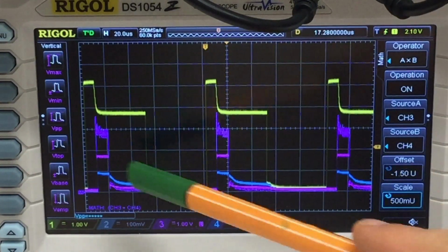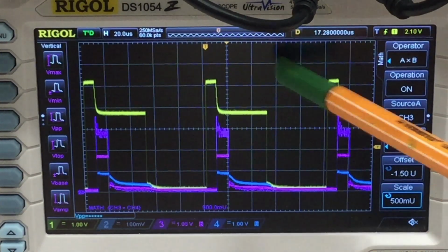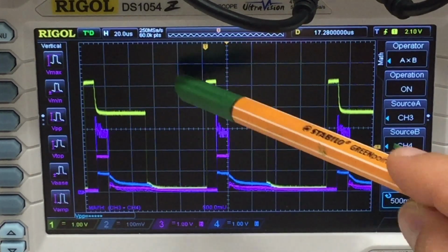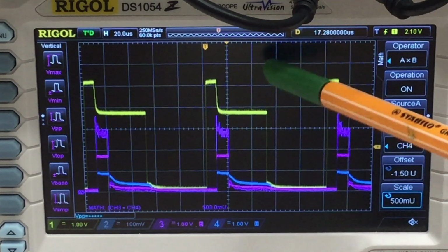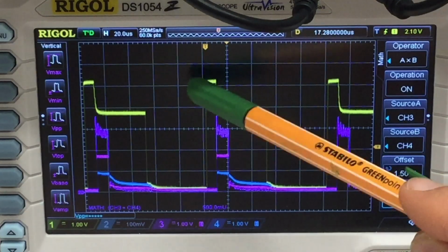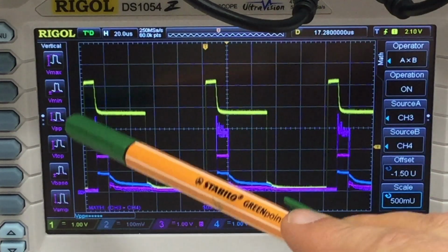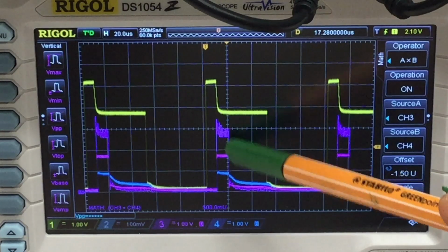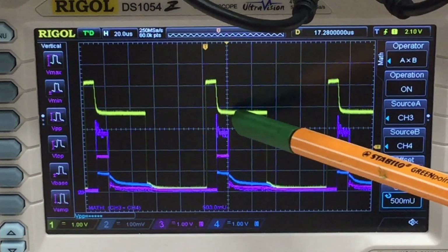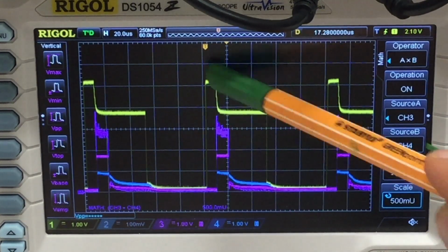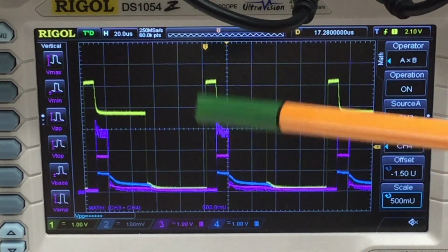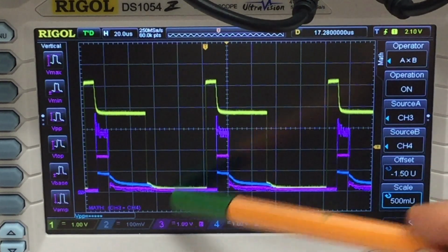So I'm feeding to my main terminal 2, that is the resistor before it, a positive square wave with a duty cycle of 50%. And to my gate, a square wave, also purely positive, with a duty cycle of 10% with a little offset to my main terminal 2 square wave. And what we can see here, we are in the off state.